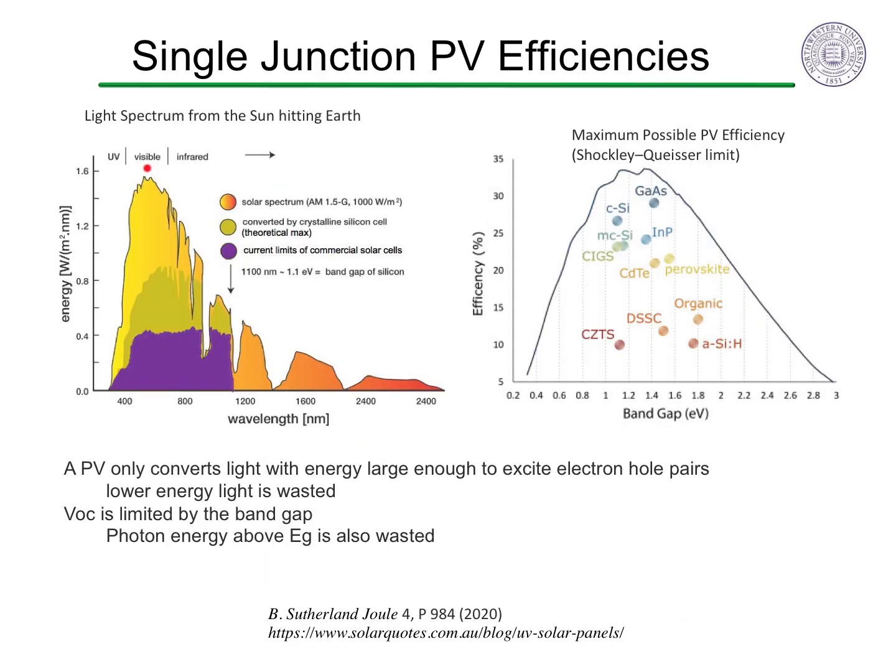Sunlight contains light of all frequencies with intensity peaking in the visible. Even a perfect photovoltaic can only convert light with energy equal to the band gap with perfect efficiency. A perfect silicon solar cell can convert 1.1 eV light with 100% efficiency, where commercial solar cells do quite well, here about 75% efficiency for the 1.1 eV light. However, all the light with larger wavelength or lower energy doesn't even get absorbed, so its energy is not converted.